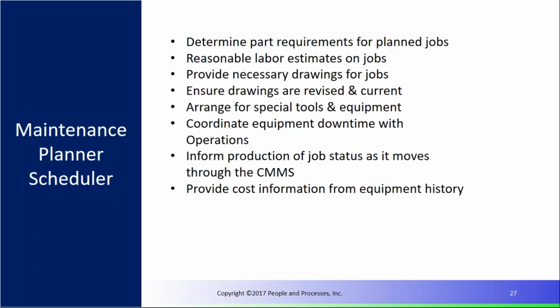What kind of parts are necessary? And that comes back into the planning. Some items, as I said, we don't necessarily need detailed job plans, but if there's ever the opportunity to leverage that, we want to do that. So what are the parts necessary? And sometimes I'll even give extra parts, meaning that I'm not sure if they'll need this particular gasket, but I'm going to include it, and then we'll turn it back in later. The intent there is to save them the travel time if they do need it. But again, you have to balance that. And what's a reasonable labor estimate?